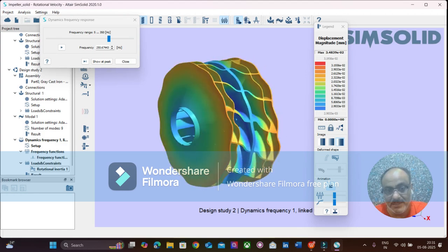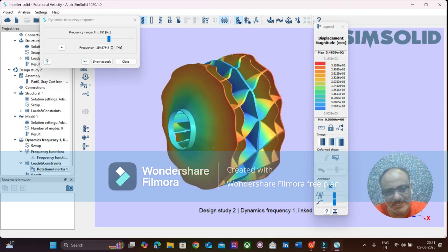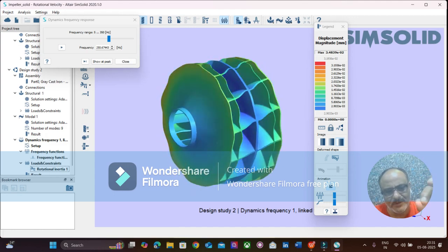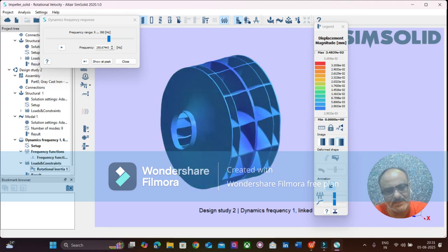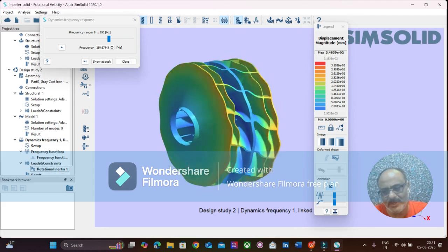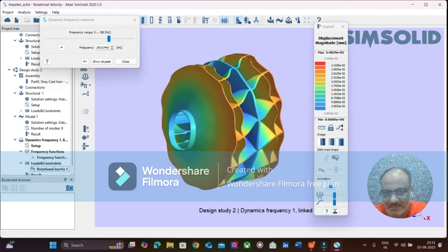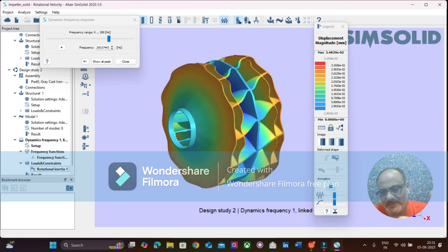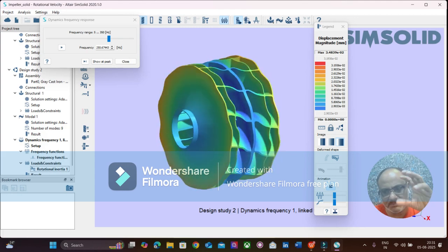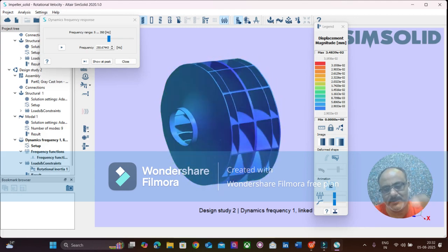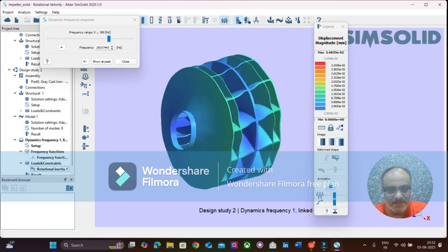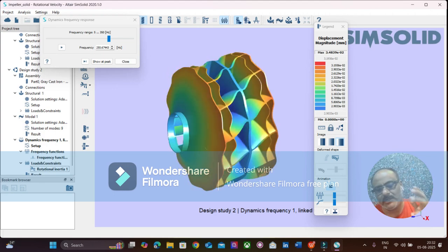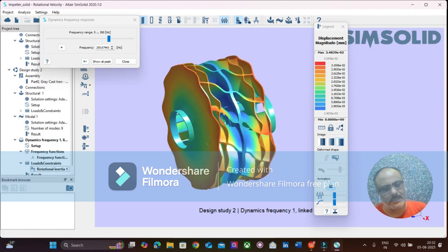Now you will find there is a torsion, and because of the torsion a lot of stresses are induced at the collar. The junction between the shroud and the collar, what we call the collar, is going to experience a lot of stresses. If the crown wasn't there, the collar would have torn off, simply because of the torsional issue. That means torsional rigidity is going to be an issue at that portion, and the system can tear off. In order to avoid that, we have reinforced it with this, which is what we call the crown.